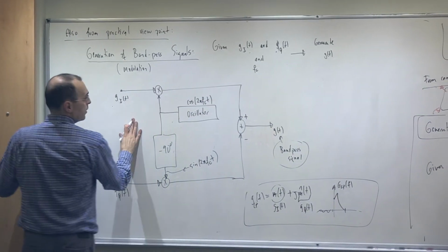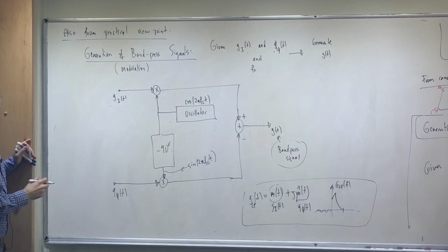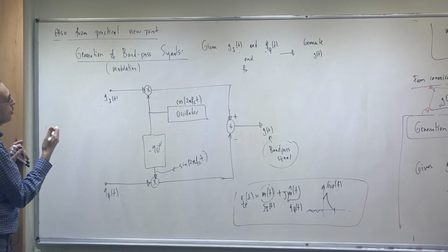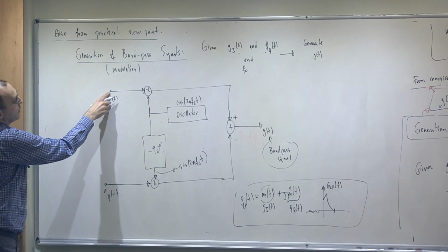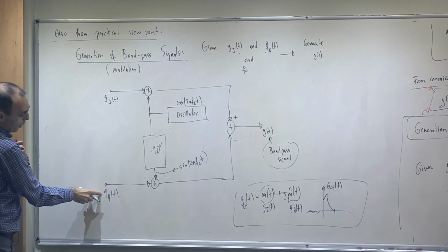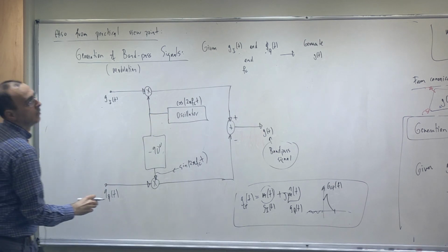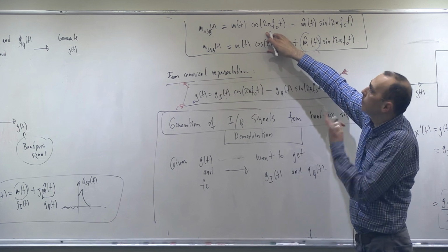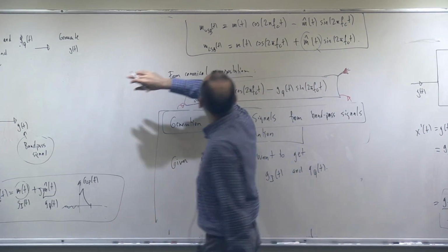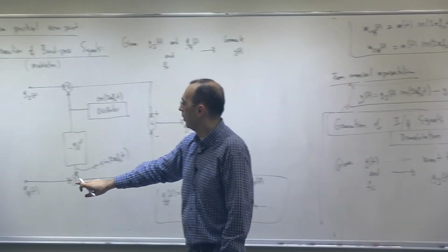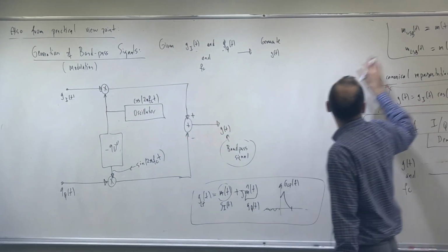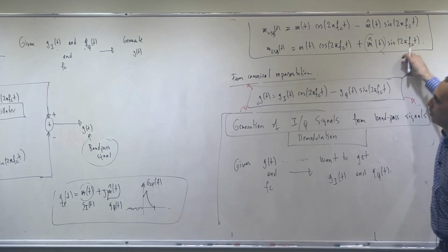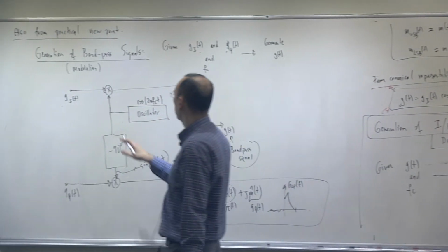So if you check this one, this is more like a radio transmitter this time. As I have said, maybe I'm just recording my song and placing it over here. This is 0. Pass it through this one. This becomes m of t times cosine, but it's not spectrum efficient. As you see, if I include the Hilbert transform of that, it becomes upper sideband modulated, single sideband modulation, and so on. So there can be different modulation schemes.